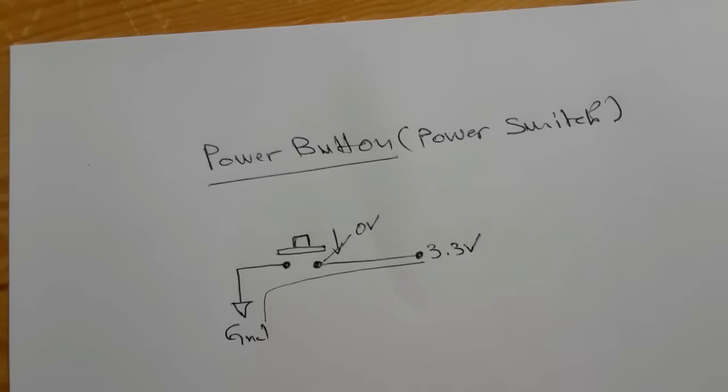Okay, so if you check one terminal of the power switch and you don't find 3.3 volt, it means the 3.3 volt is missing. If the 3.3 volt is missing, you cannot switch on or power on your laptop.